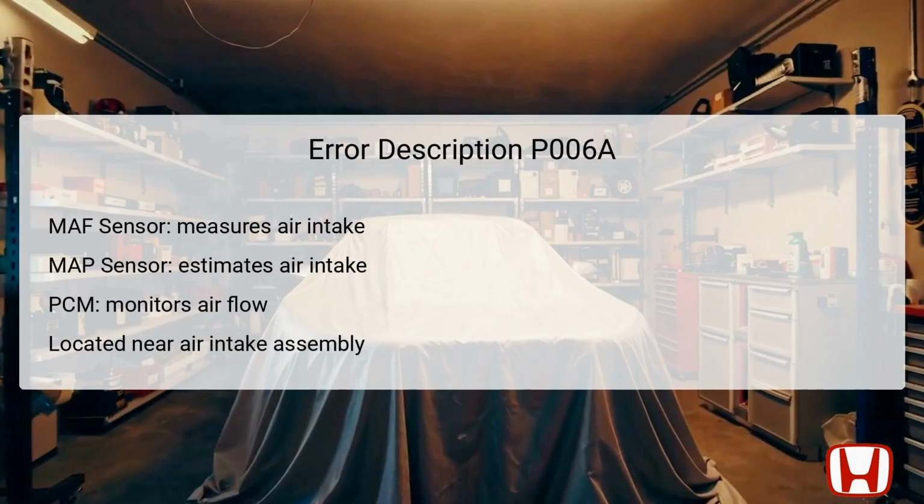The mass airflow MAF sensor is responsible for measuring the amount of air entering the engine, allowing the powertrain control module, PCM, to adjust fuel delivery accordingly for optimal combustion. The MAP sensor, or manifold absolute pressure sensor, estimates air intake based on pressure variations in the intake manifold. The PCM uses these readings to ensure the engine operates efficiently.